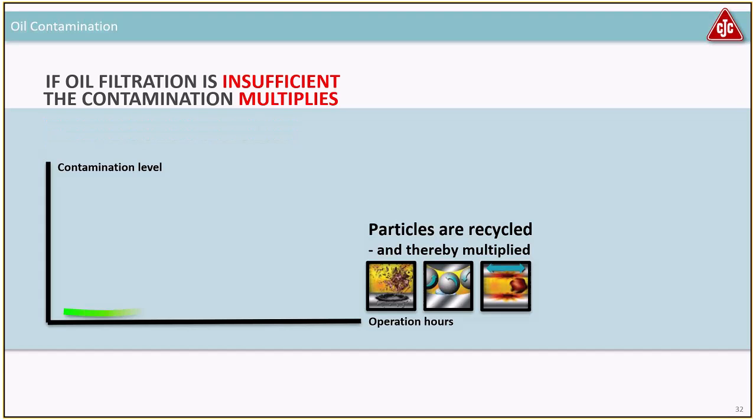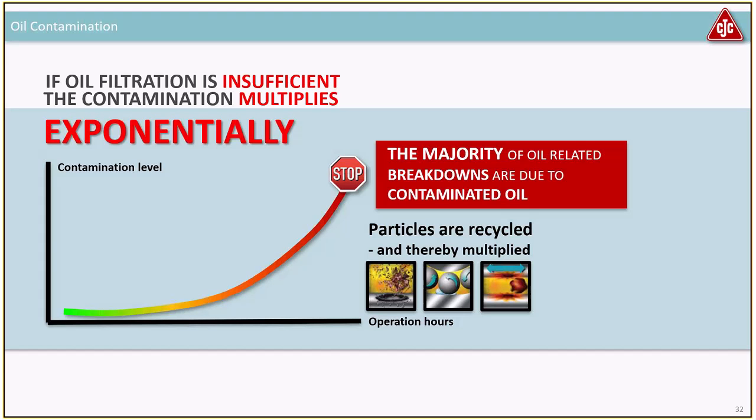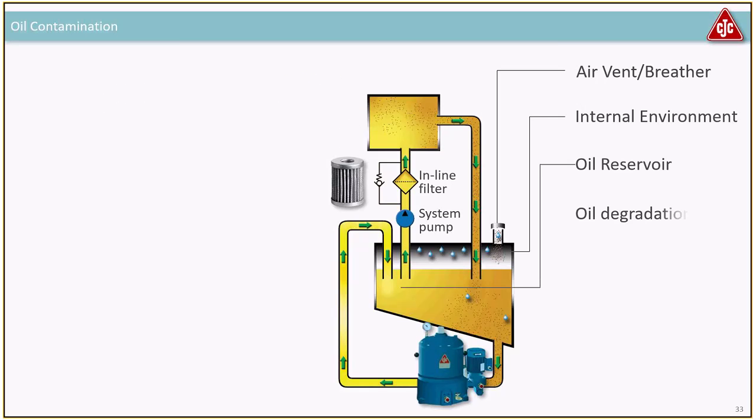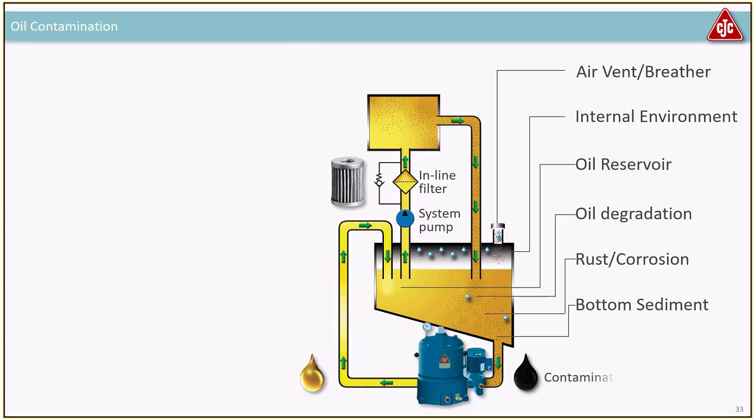Yes, so when you have dirty oil, it will exponentially create more and more wear in your system. And like I said in the start, studies have shown that the majority of breakdowns are actually due to contaminated oil. So some particles that are getting in will create more wear, more particles. So we need to get rid of this as soon as possible. So you can actually do that by using three types of filters. So you should stop the ingression of dirt and water.